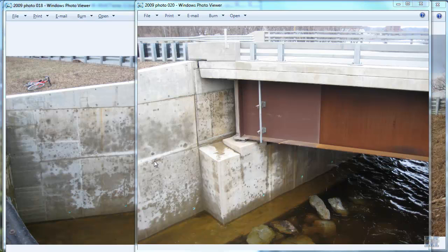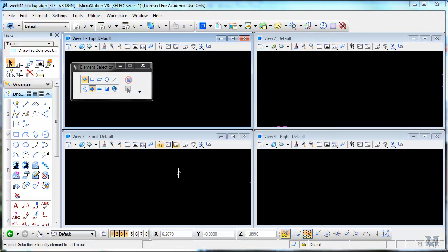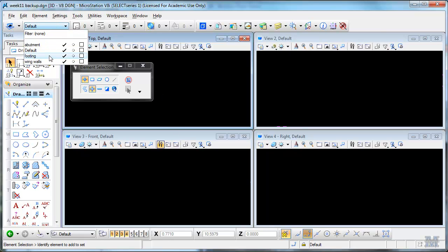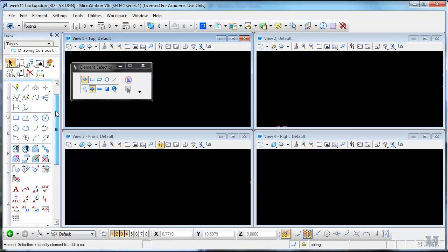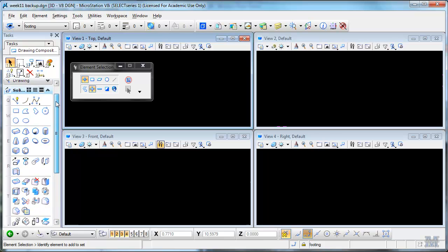And then to the left over here is the wing wall, which goes, in this case, pretty much straight across, but note that it tapers down, supporting the earth behind it. And then on the opposite, so in MicroStation I started with a 3D seed file, set up a few levels, and what I'm going to do is start from the bottom up like you'd build it, with the footing, and draw that in. I'll start with a slab in the solids modeling group.